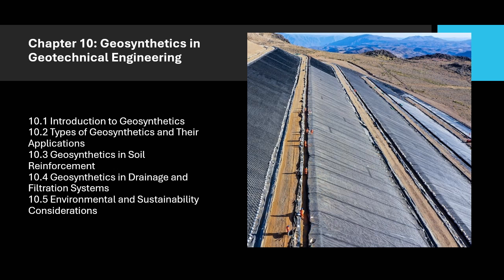4. Geocells. Description. Geocells are three-dimensional cellular structures made from polymers used to provide confinement to soil or aggregate. Applications. Slope stabilization, erosion control, and load support in areas with weak or soft soils. Strengthening foundations by distributing loads over a wider area.